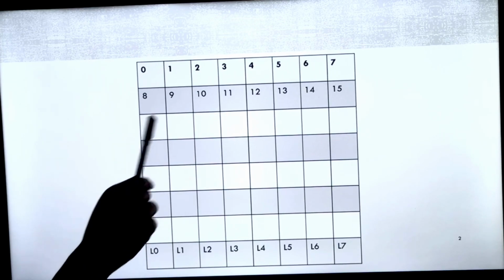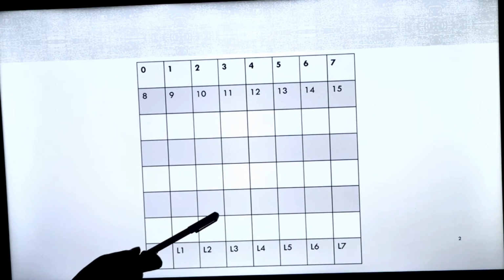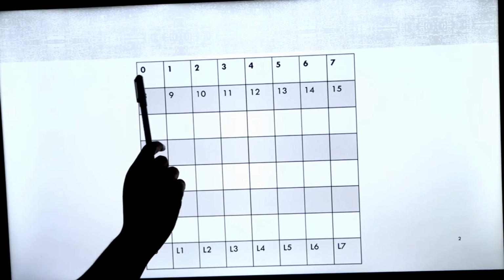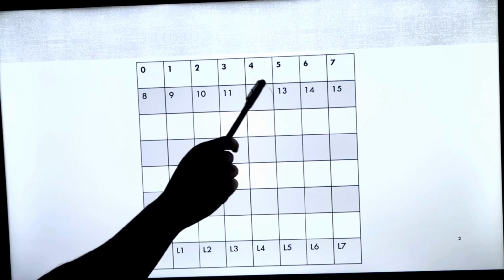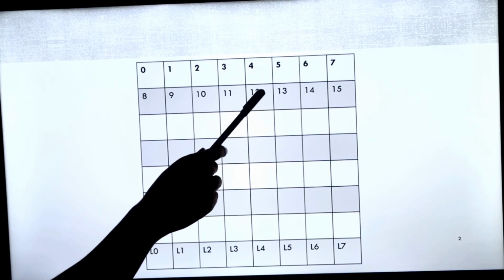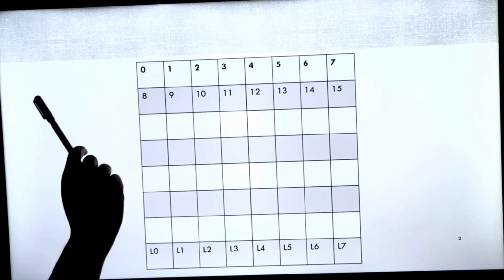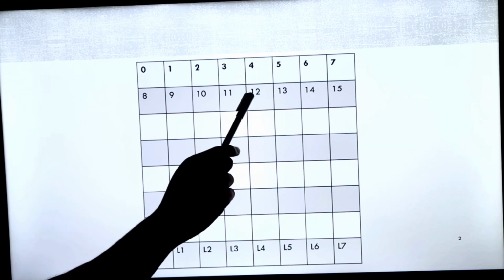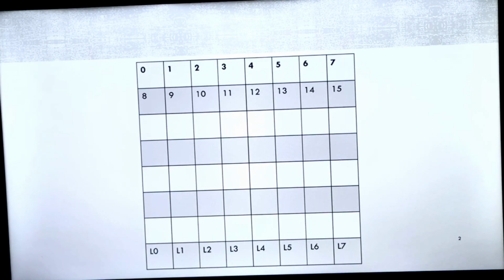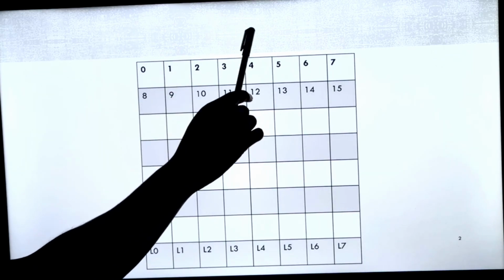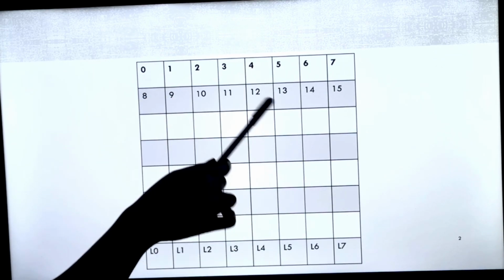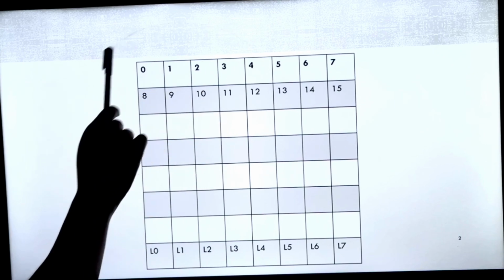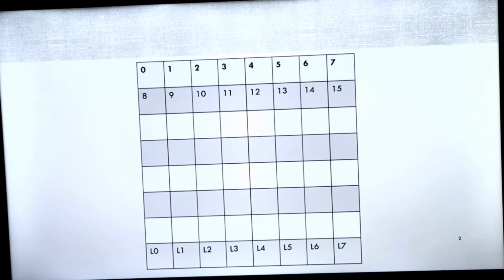You understood that? Suppose in this example or in this diagram, I have 1 bit stored here in address number 12. So I am numbering from 0 to n. This is the 12th address I have, and here I have stored something. Whenever my processor needs something from this particular cell, it won't ask for the data directly. Rather, it will send the address. What is the address? 12. So inside 12, whatever is there, I don't know. It may be any information. Your processor will ask your memory to give the data or information present in address number 12. And then your memory will give the data to the processor to perform specific tasks. This is how it communicates.